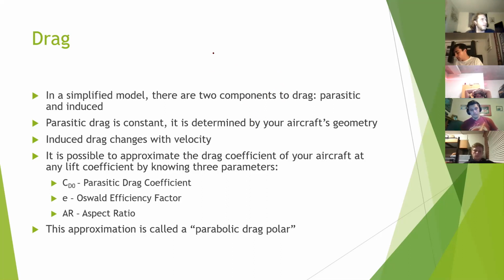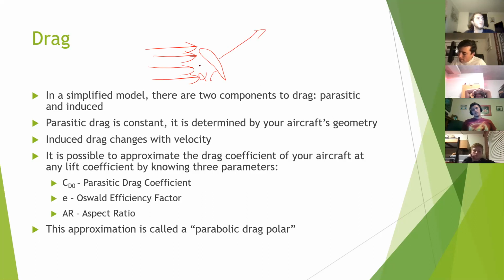And then induced drag comes from the fact that if you have an airfoil at some angle of attack with air coming in here, right? Again, ludicrously large angle of attack, don't worry about it. You've got a lift force that does come up normal to your airfoil. But we don't care about anything in that direction. We only ever want to know the vertical and horizontal components, because that's our lift that we care about and that's our drag that we care about. And so this drag is our induced drag.